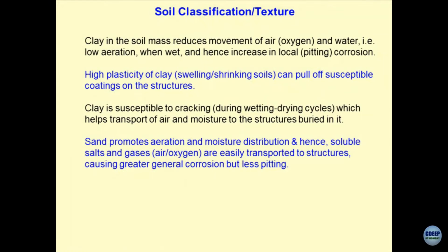So, when you have given this type of coatings to the piles or the buried structures, this could be culverts also, this could be the foundations also, if the soil is shrinking and swelling type, what is going to happen? Every time the soil comes in contact with the epoxy, it has a tendency to rip off the epoxy. So, this becomes detrimental, alright.